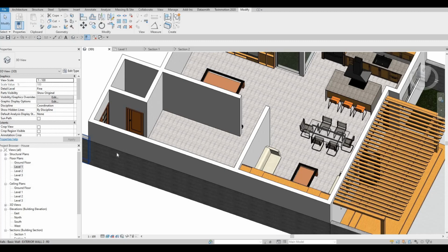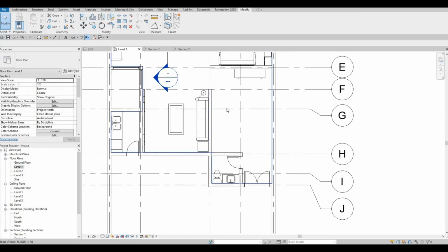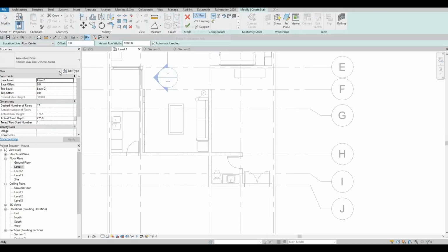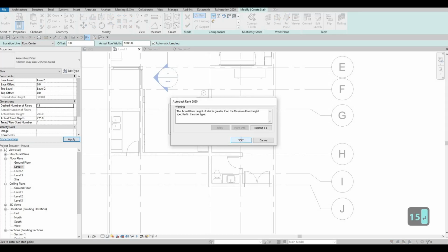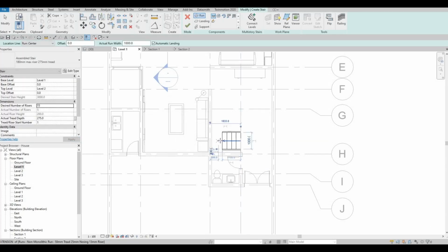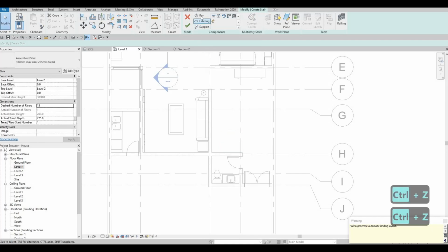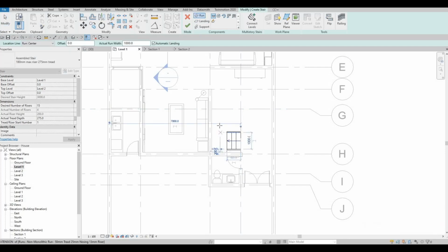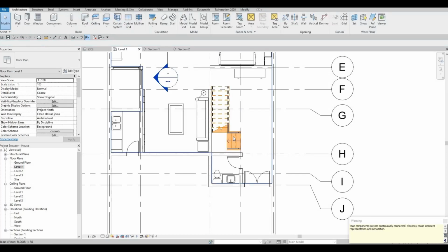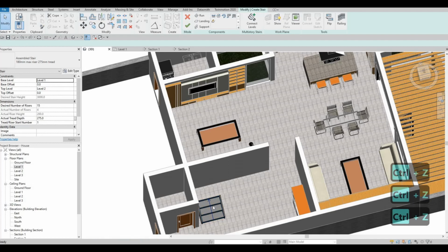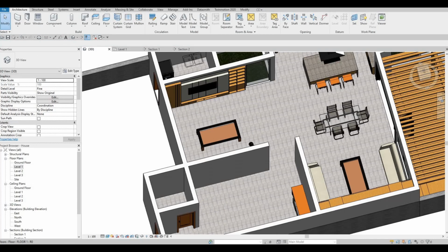And then now what I want to do is to create the L-shape stairs. So here what I'm gonna do is click on stairs. I'm gonna use this first, and then maybe I want it to be around 15 only. Press OK, and then let's create this all the way at the top. I want to have a landing there, so I'm going to create this with a landing. So the landing didn't work, so I'm just going to close this first. So let's try this again.